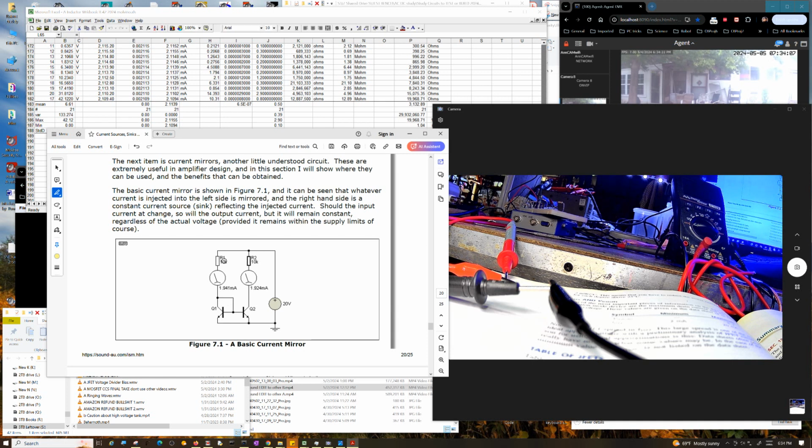So in theory, you could detach R1 here and tie it to a different voltage source, like the output of a unity gain op amp, and that can handle 20 or 30 milliamps, whatever current you wanted to allow through this thing.